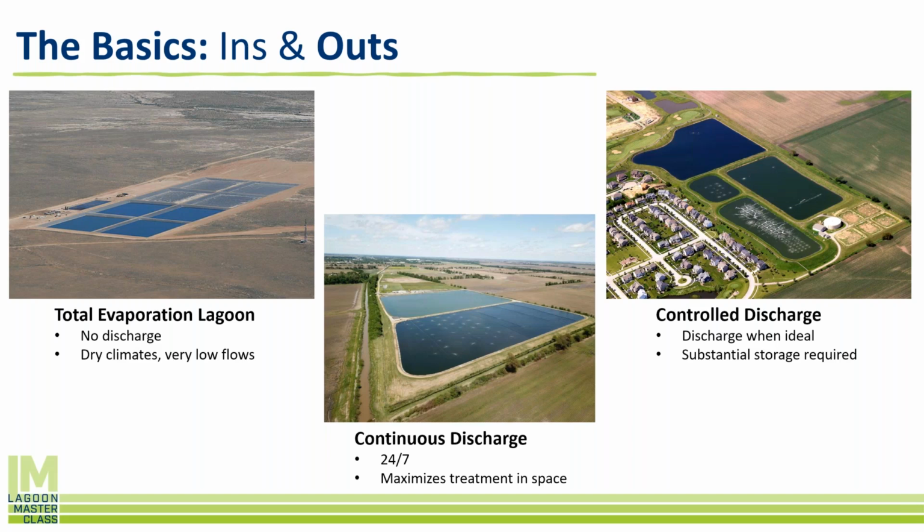And when the late summer months come around, the stream starts to dry up, the amount of water moving through is less, which means there's less dilution for the water that we're putting into it. And generally regulators will put more stringent limits when the flows are lower. So some facilities will say, hey, we're gonna hang on to the water until a good time to discharge into that receiving river or stream.